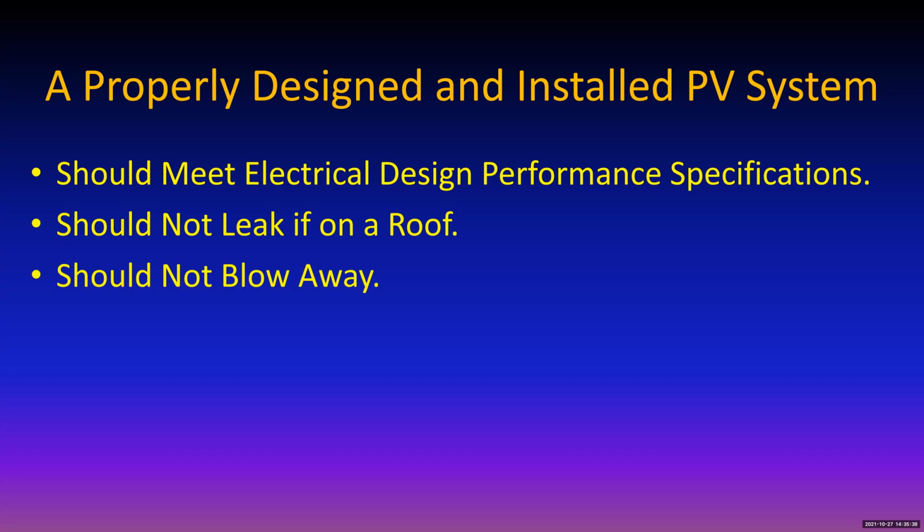It better not blow away, because after all, if you want it to provide power for you after a heavy windstorm, it's got to stay on the roof. Now, these things are bolted down to your trusses with 4-inch lag screws, and your roof decking is certainly not anchored to the trusses with 4-inch lag screws.